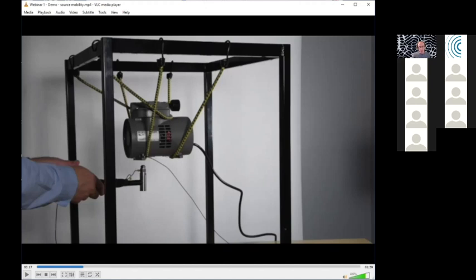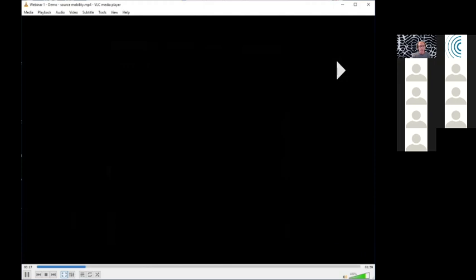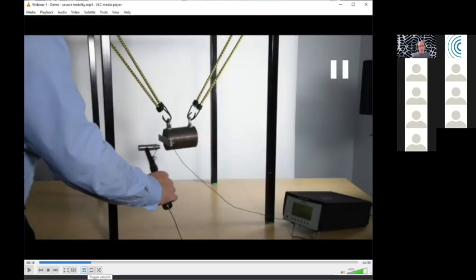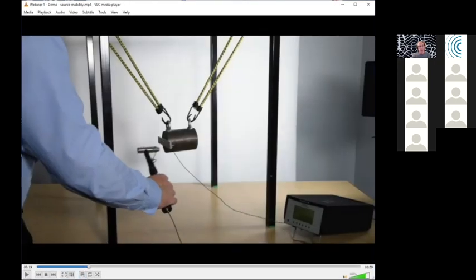So on the basis that this machine might be considered as a kind of lump mass here, we'll return to take some more measurements on that calibration mass that Gary showed you. And then we're going to modify it under Barry's suggestion of adding a small cantilever to represent these kind of fixing points. So we return to the calibration mass. So here's that cylindrical mass from before that Gary used to calibrate the force transducer.